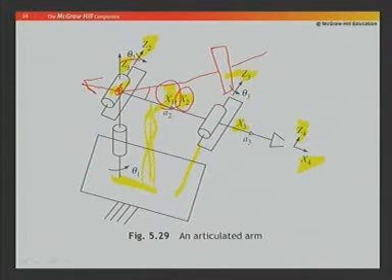So, we have done the first pair of joints. Now, move to the second pair of frames. So, B2 is the offset between x2 and x3. So, this is my x2 here and this is also x3 here. So, there is no offset. So, B2 is 0.